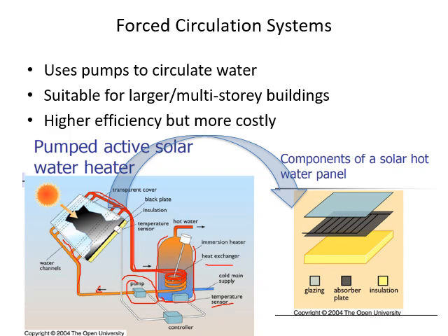And for your forced circulation system, you also need to design the collector in a special way. There will be a glazing panel at the top that will protect it. Under the glazing panel will be the water tubes distributed, and underneath it will be the insulation, because this thing acts as our heat source, right?